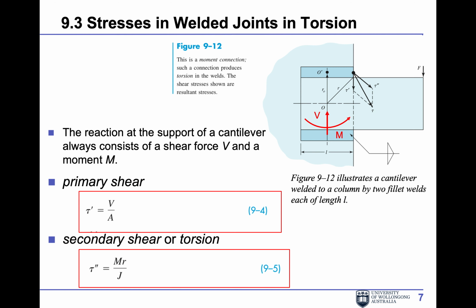Then case 3 is when the weld joint is in torsion. So you have a moment over there. If you start with a force applied at the end of the weld, and this weld symbol, two triangles, means you have one weld at the bottom, on this arrow side, and one at the top on the other side. You have two welds over there.